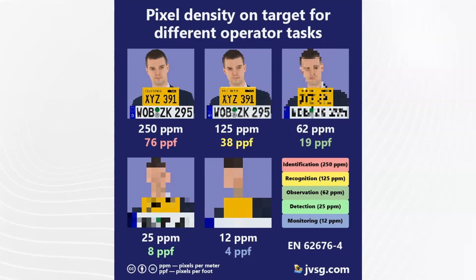So when you design the system, it doesn't matter what kind of brand you are using right now. When I'm talking about the cameras, you can ask the manufacturer for some kind of specification for their video analytics, and ask them how many pixels per meter. This is the quality that you calculate. How many pixels per meter you need for proper detection. So if your manufacturer is stating that our AI can detect a person with 99%, you should ask how many pixels you need for this 99%. Because this is what we need. We need to design this way.